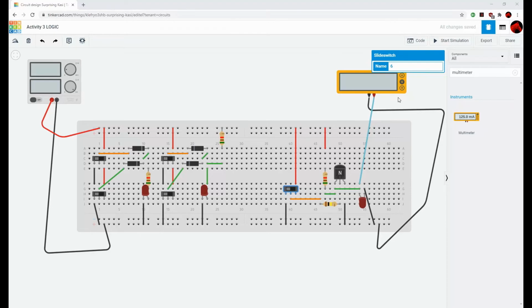And that is a perfect example of why I tend to set current limits in the real world on power supplies when I'm first turning on a test circuit. That wouldn't have happened. Typically, I would have set this to 100 milliamps instead of allowing the power supply to drop 5 amps through the breadboard, which I guarantee you right now in the lab would cause melted plastic and a nasty smoky smell. Check, double check, and take precautions.